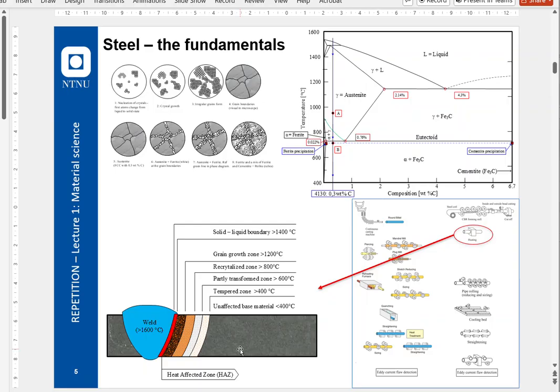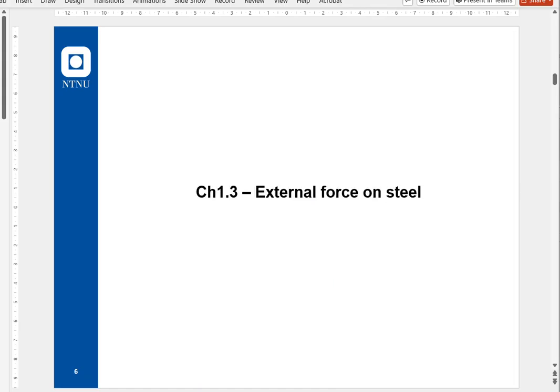And everything is according to the phase diagram, as we can see here. Heating it up to, say, 400 plus degrees, changes are quite rapid. You can say that, for example, a piece of casing normally would need an hour, and then it's fully recrystallized into whatever size that we want. We talked about recrystallization when it comes to welding being very important. And with that, I think we have recapped the latest lecture.